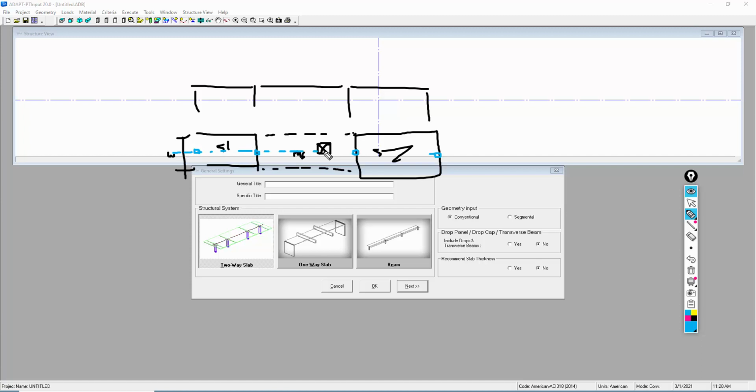So we have this datum or center line that we're referencing. We'll call it a reference line, RL. And so we cannot model an opening away from the reference line. In other words, I couldn't puncture a slab here where there's a gap between the reference line and the face